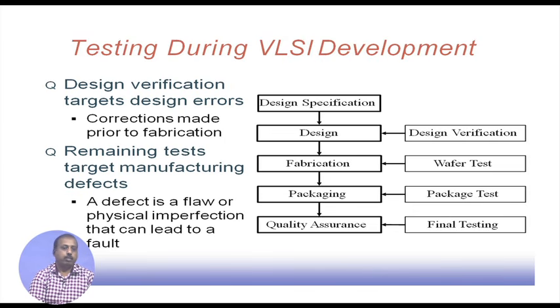If count becomes 15, then count will be reset to 0. That way we can write in some hardware description language. Now, when converted into a counter design, it will possibly have 4 flip flops in it, and associated gates will realize the same functionality.